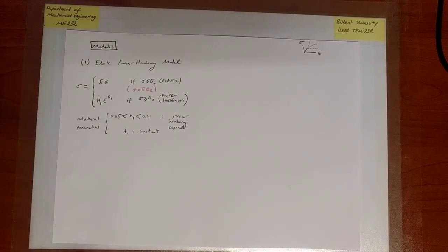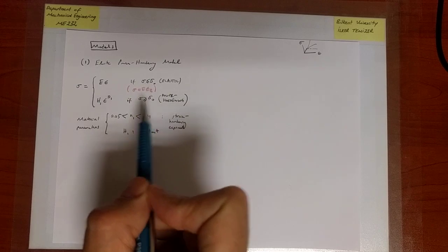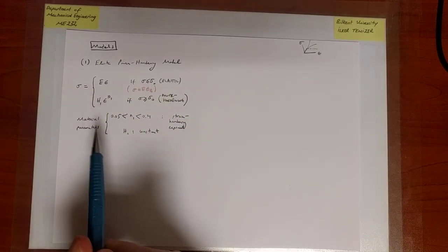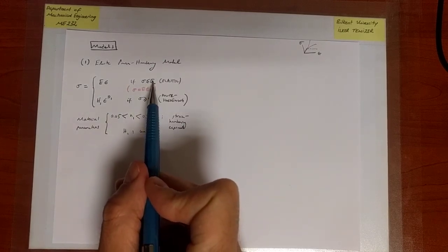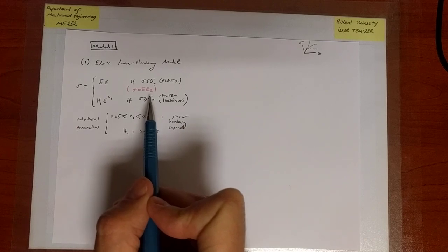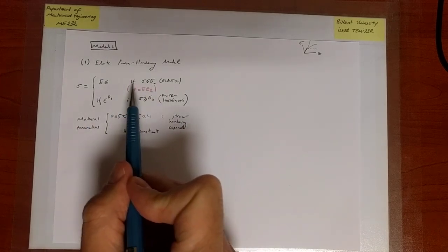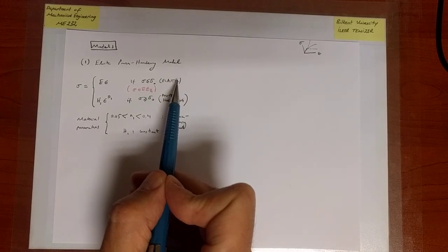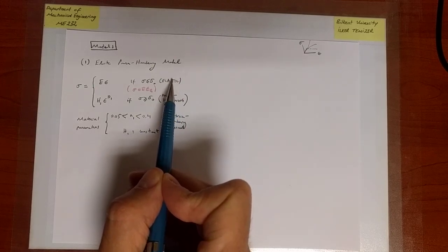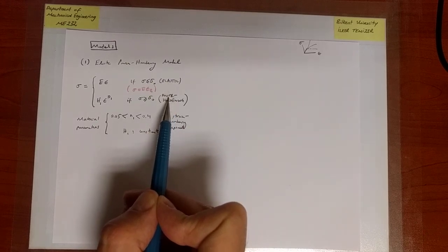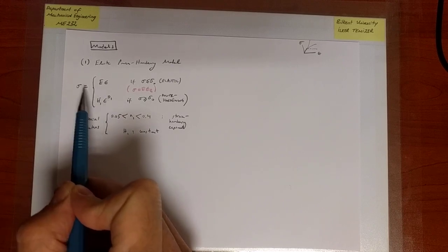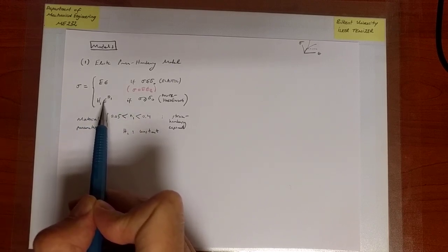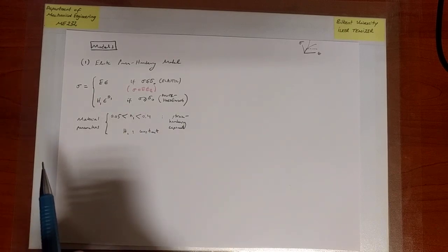All right, so at this point, what I seem to have is a model that is able to predict what happens in the elastic and plastic regions, provided I know the values of H1 and N1. But I also need to know the value of the yield strength of the material in order to apply this model, because the model has two legs. I need to check, first of all, if it's in the elastic zone. If yes, I can use that relation, but if not, I need to use this relation. So you give me the value of strain, I can still predict the stress. That was our purpose, remember. That's our modeling target. But to do that check, I need to know the value of sigma naught.